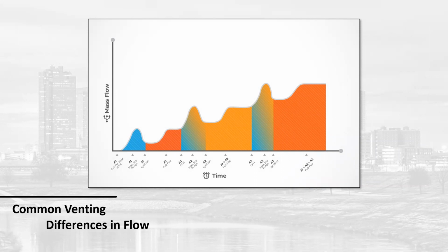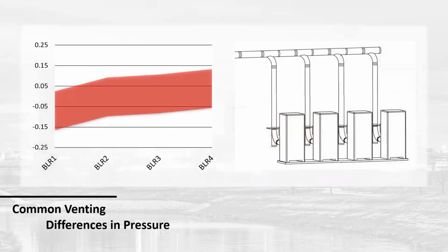Because then you can, the way that controlling those boilers work and various things. So the problem is that when you have a stack sized for the full load and you only put in, say, 15% of that load, you're going to have all kinds of flow issues. So as you can see, the mass flow of that system is constantly changing as you turn boilers on, as the stack gets primed, etc.